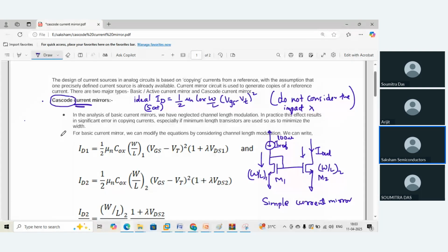If my MOSFET is biased in the saturation region, that means a constant current is flowing during the saturation region of operation, and the graph of that current would look something like this. But that also means this current is not a constant entity, it has a small incremental value, and that gives rise to finite output resistance R naught, which is accounted for by the term lambda.